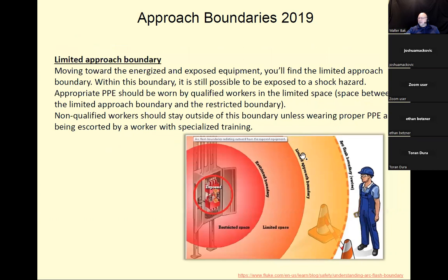All right. Then here's the limited approach boundary. Moving towards the energized, exposed equipment, you will find the limited approach boundary. If you come closer than that, within this boundary, it is still possible to be exposed to a shock hazard. Appropriate PPE should be worn by qualified workers in the limited space between the limited approach boundary and the restricted boundary. So that's here, between here and here.